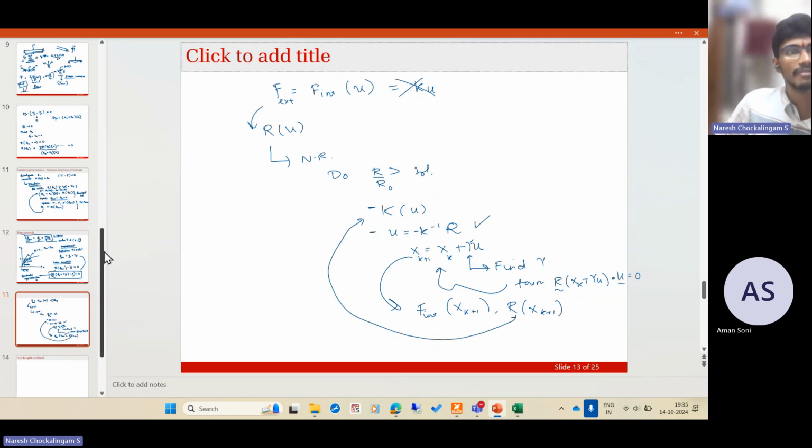So this line search is a variant of the Newton-Raphson, where inside the Newton-Raphson, you're solving another equation to find how much you have to move along the tangent direction. So you get a tangent. In Newton-Raphson, you invert the tangent and go the full distance. But in line search, you don't go to the full extent. You get a tangent, but in that direction you go only some distance, and from there you take another tangent. That is what we do.